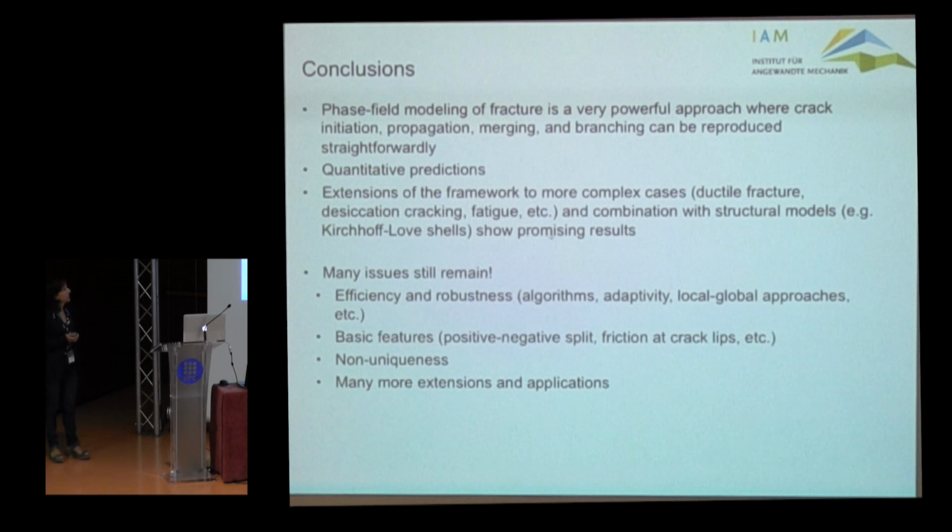But there are many issues that still remain. The main issues are efficiency and robustness. I'm thinking about algorithms, but I'm also thinking about adaptivity schemes. I'm also thinking about local-global approaches to examine the crack in detail in the regions where this is needed. And there are basic features of the model that still are unclear or are still not satisfactory. One of them is the positive-negative split, but for instance, you may also want that crack faces develop some friction once the crack recloses. In a non-monotonic case of loading, you have this issue of non-uniqueness, which needs to be tackled somehow, and there are still many, many more extensions and applications that are waiting to be tackled.